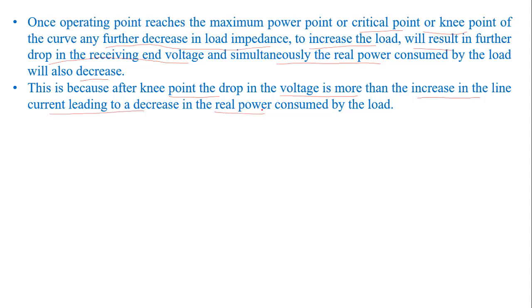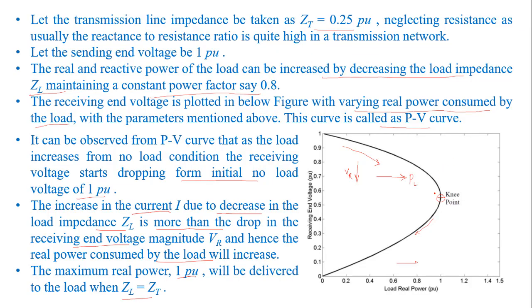So here after the knee point, we can see after this knee point, the decrease in voltage is greater as compared to the increase in the current. So therefore what happens, your load power decreases in this region, the load power decreases again, falls. So you can see here after the knee point the load power is decreasing, simultaneously the VR is also decreasing.